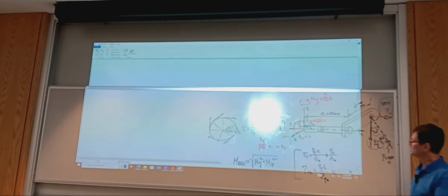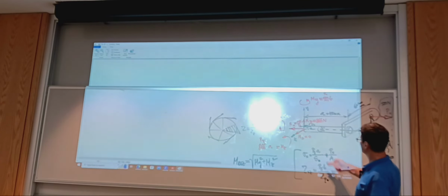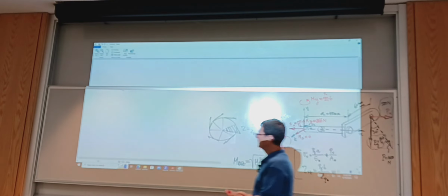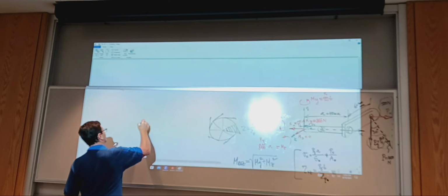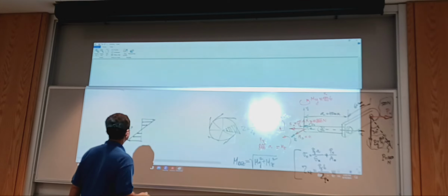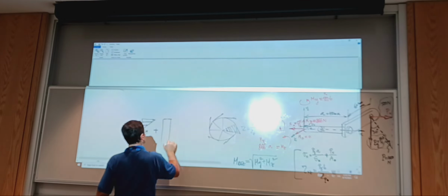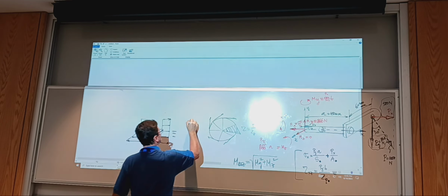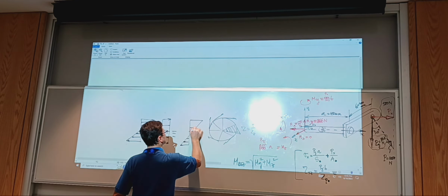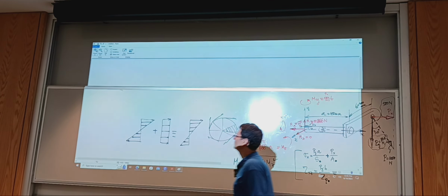Okay. So this is where you would see a term like force over area, even as uniformly distributed. The book has it drawn in several places. So for a round bar, the bending stress has an equal amount of tension and equal amount of compression, and then you add the direct tension due to an axial load, and it gets you more tension and less compression. I drew this at least twice before.